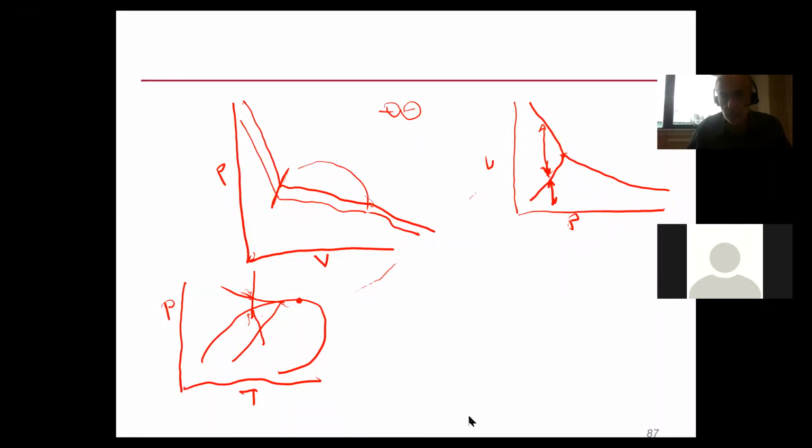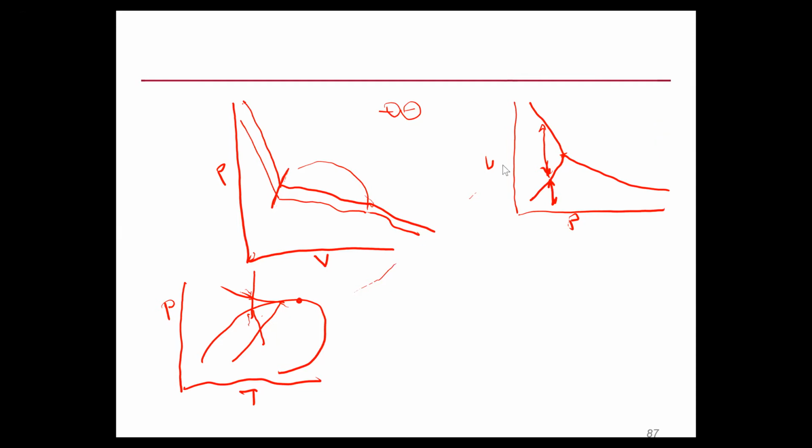So what we are discussing is the various processes that can result in asphaltene formation and deposition. One of the processes that can result in asphaltene deposition is depletion, that when we produce the oil, and asphaltene is a function of pressure and temperature.